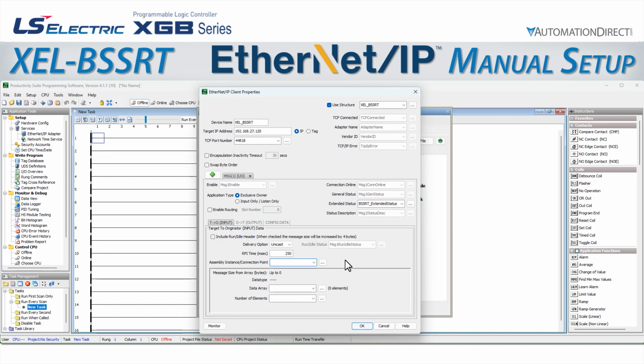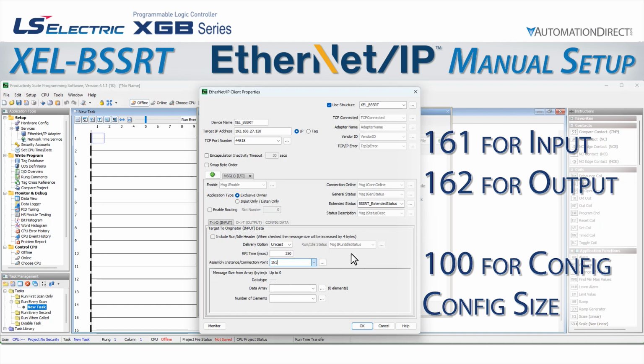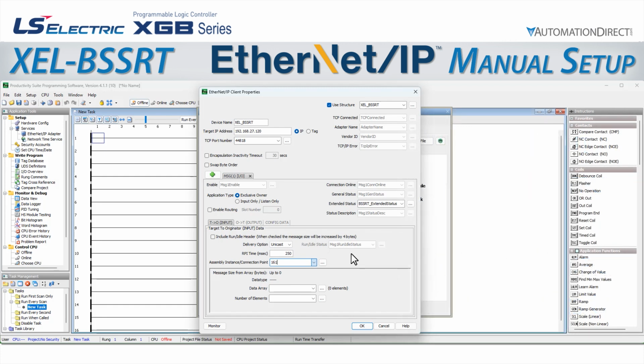The assembly instance information for input and output on the BSSRT is listed in the help files. It is instance 161 for input data with no run idle header, and 162 for output data with a run idle header. Since the BSSRT doesn't use config data, it will allow a connection at instance 100, but the data size for the config data must be 0. That just leaves the data entry for the input information. The BSSRT uses a minimum of 16 bits for each input or output data section, so we can use a 16-bit word array for the data processing.